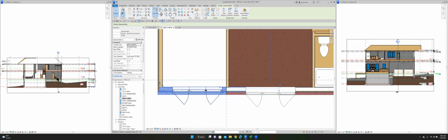And I want to pull that wall back just to take a look at the 3D view that I have so far. I want to split this wall so that my gable is across here, and then this is back, so I have some definition. So I'm going to go back to the first floor, and I still have that highlighted, and I'll just move it back 2 feet. So click anywhere on the screen, and then use the mouse to show the direction that I want the wall to move. And then I use the keyboard, just type in 2, and that should move that wall back. And sure enough, it did.